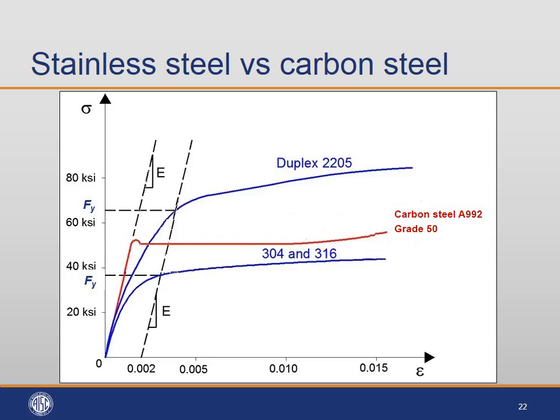I think you just need to make some general engineering judgment. I've laid out the facts to you about the nonlinear stress strain curve. You'll just have to make some simplifying assumptions based on what you know. I think in the compression chapter we do talk a little bit about torsional flexural buckling, but basically it's just going to have to be a conservative design assumption.